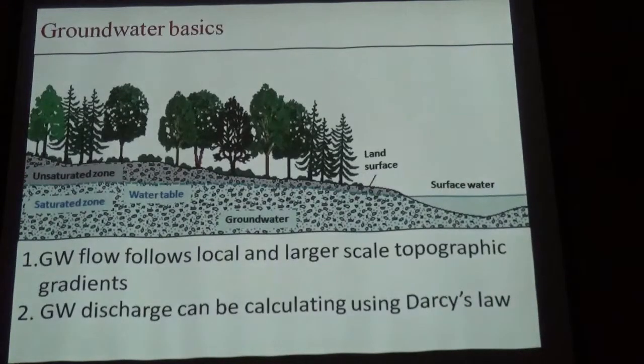But I'm going to show you today the principle. How do we use this radon? So we detected it. What can we do to calculate how much water comes out, not only where it comes out? Usually when we do this research, we first do these surveys. We detect where those sources are, and then we use the same instrument and put it in a station and measure radon continuously in this place to calculate how much fresh groundwater is coming up.